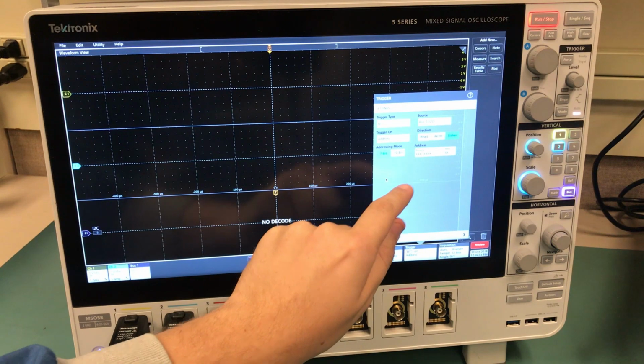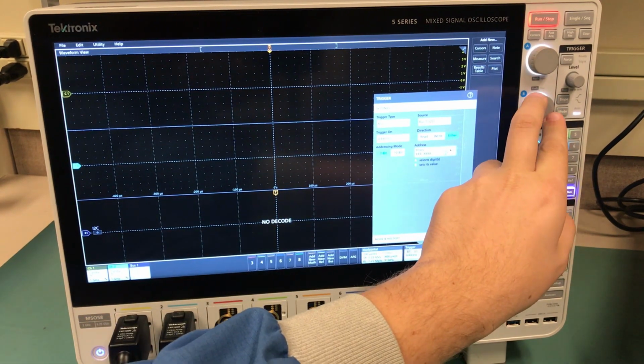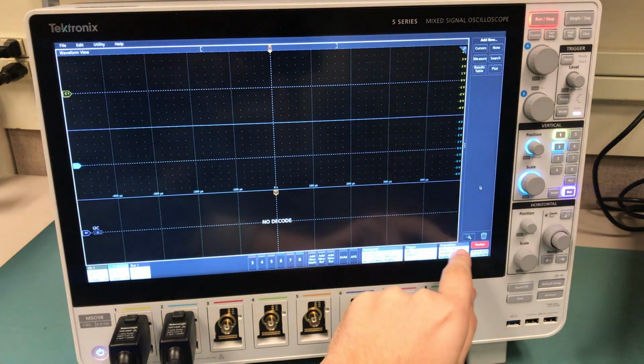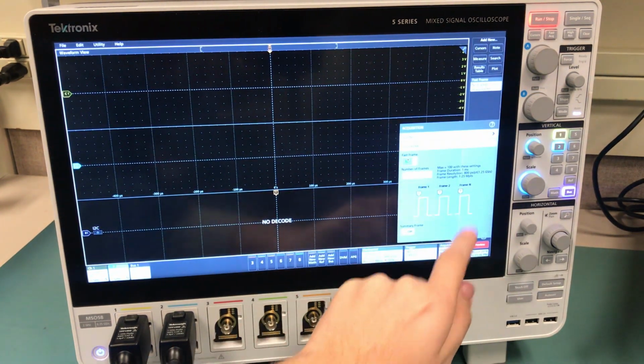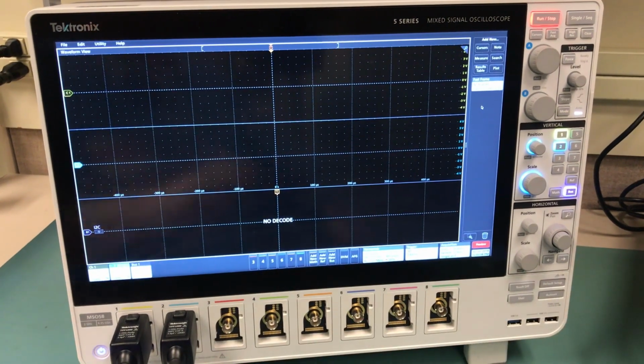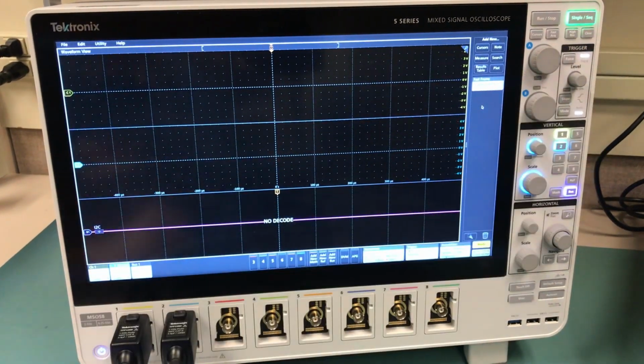As you can imagine, we'll be using this feature to look at differences in how the bus starts up from nothing and how it starts up after a dropout. Our 1 millisecond dropout is indeed enough for the I2C bus to restart. Okay, so now I'll enable the scope's trigger and then on the SMU trigger our pulse again.